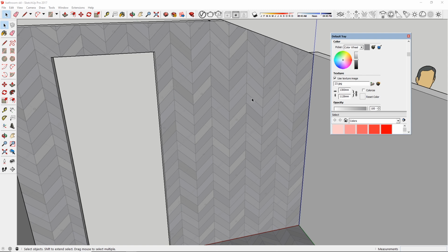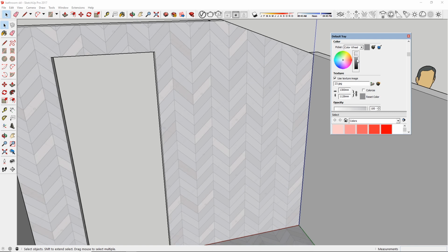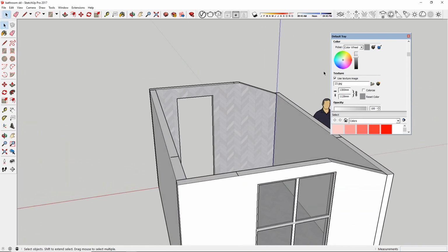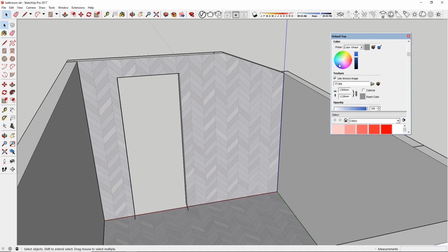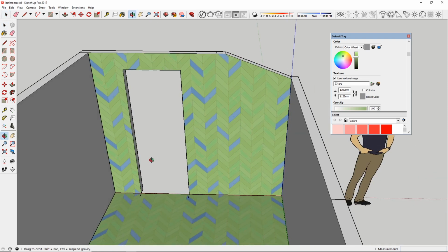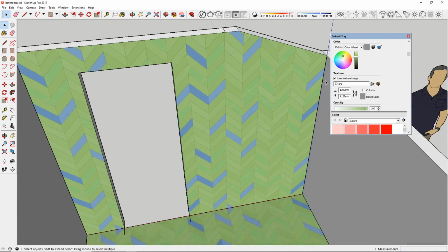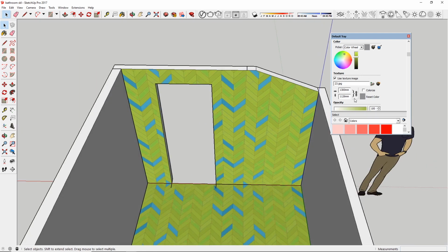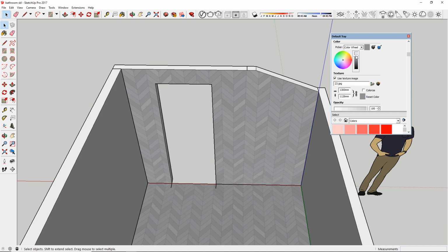You might find difficulty finding something exactly that you want, but with a bit of editing, you can even edit, say if the color is still quite off, you can just edit it within the SketchUp editor, which is quite nice. So if I want it a bit lighter, I can just do that, and it's made it a little bit lighter for us. And again, if you wanted to change the color a bit, you can just adjust it. Oh, that's kind of interesting, isn't it? Say if it's a white tile, it should adjust a bit better than this, because obviously there's an offset issue here. And if you want to reset the color, you can just hit this button down here, and it resets. But I'm going to leave it slightly like that, which is great.